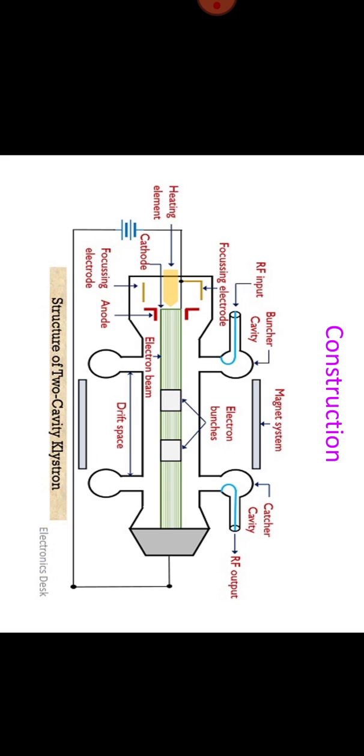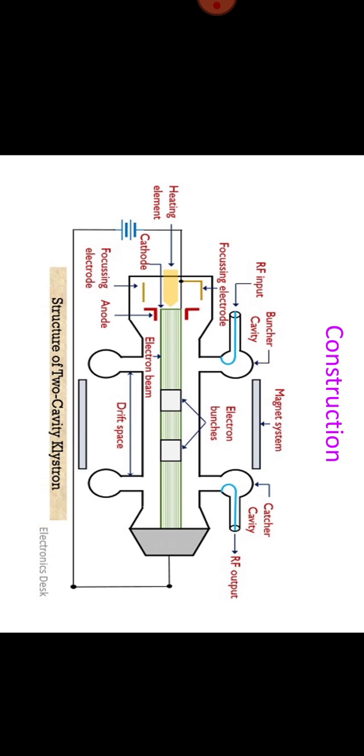Usually the klystron is a narrow bandwidth device because of the need for cavity resonators. If all cavities are tuned to the same frequency, a condition called synchronous tuning, the bandwidth will be of the order of 0.25% to 0.50%. For example, a 5 GHz klystron that is synchronously tuned and has a 0.25% bandwidth requires an input signal within plus or minus 6.25 megahertz of 5000 megahertz.